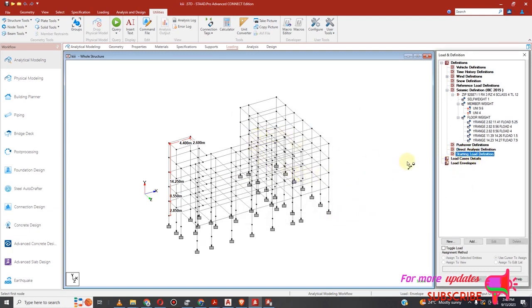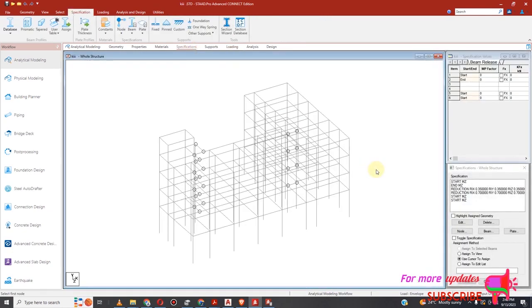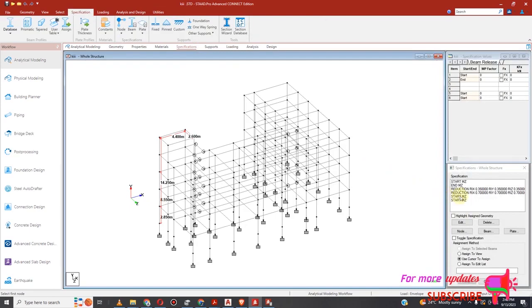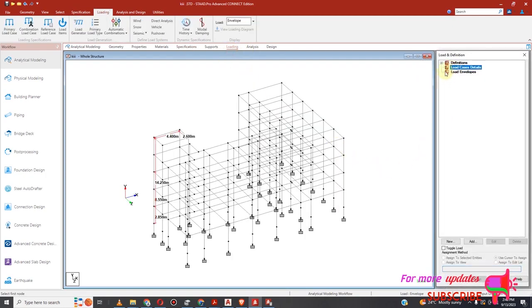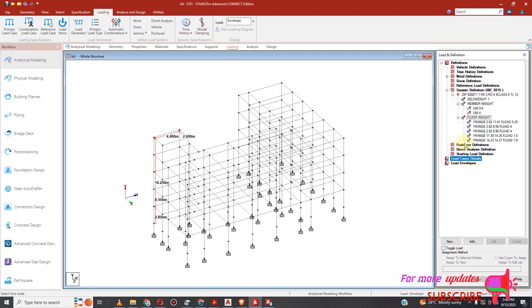Okay, so good. First of all, let me check if I included my diaphragm. So first of all, I'll delete these ones. So let me go back to load cases. So Seismic here, yeah. So I think we are done with Seismic loads. So the only thing we are left with is to assign these member loads to the relevant walls and also the parapet.